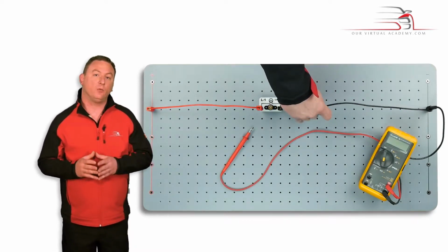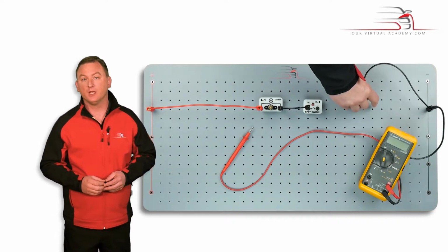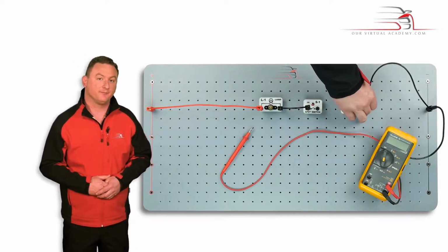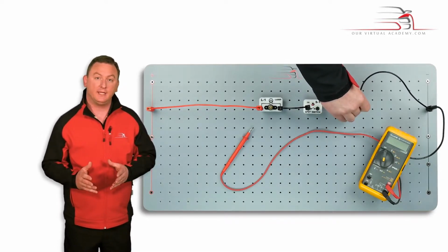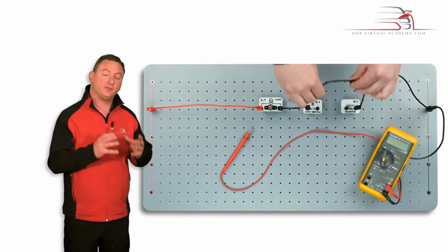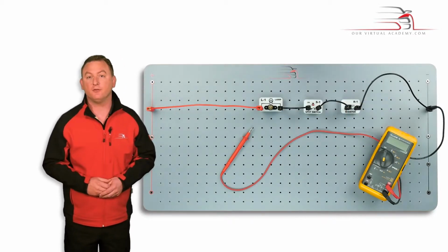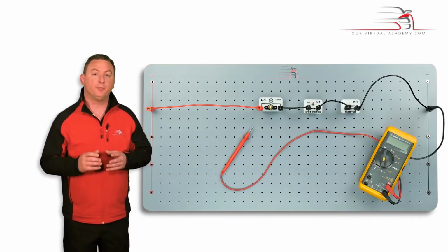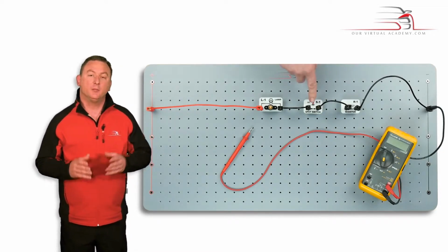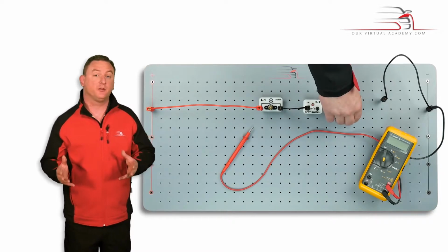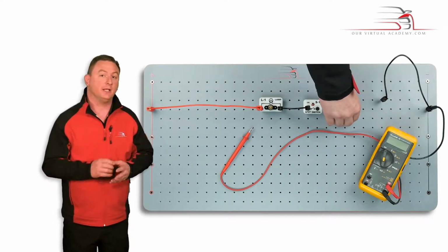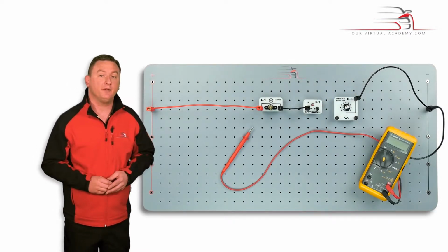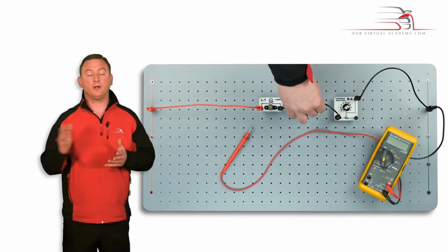But what if I didn't want the bulb at full brightness? What if I wanted it to be half its available brightness? How could this be achieved? Well, one way would be using a resistor of the same value as the bulb wired in series. This would be a very good solution if I always wanted the bulb at that brightness. But I may want the bulb perhaps a third as bright, which would mean a different value of resistor.